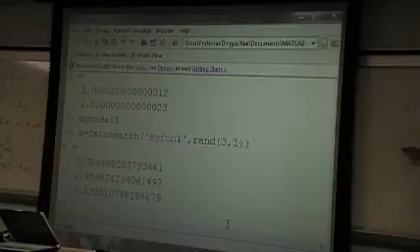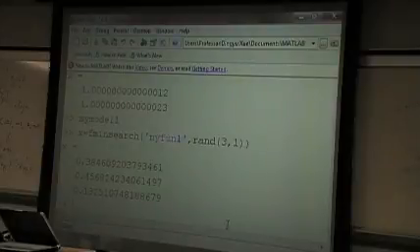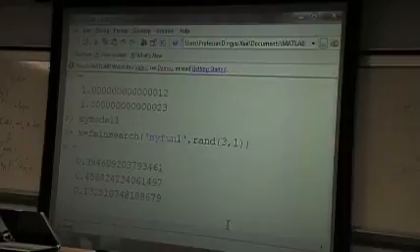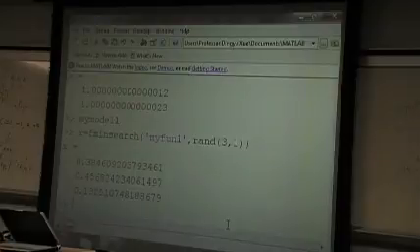If you read control literature, you find that most people use this criterion, and it is also the H2 norm. And also you may have IAE, which is quite similar to ISE. So let's demonstrate how we can implement this, and what the result is.